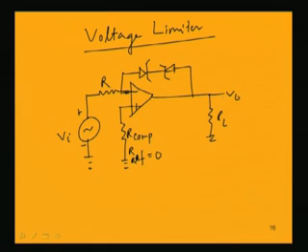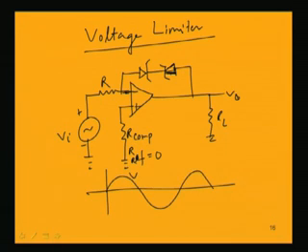Now, in this circuit, as two Zener diodes are there, obviously their Zener voltages must be lesser than what you get at the output, the saturation, that is 14 volt, it should be less than 14 volt. Now, what will happen when we have the input voltage sinusoidal is given, this is V peak, this is minus V peak. Now, in the positive half cycle, let us consider this half cycle. So, the reference is 0 of course.